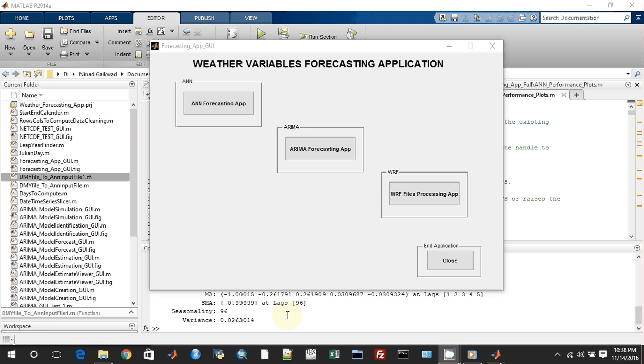And what I would like to add is that this application is useful for data acquisition and data slicing, model identification using stationarity, ACF, PACF concepts, then creating apps, creating ARIMA models of all the available options from MATLAB Econometrics Toolbox, model estimation and fitness check using normalized residuals, PACF, ACF of the residuals, and AIC, BIC values, and finally model forecasting and storing forecasted values in Excel sheet.